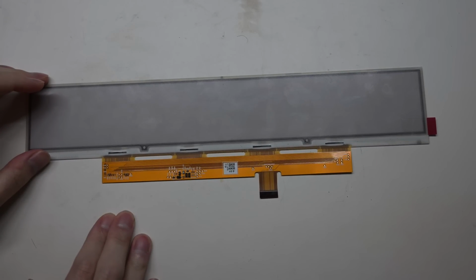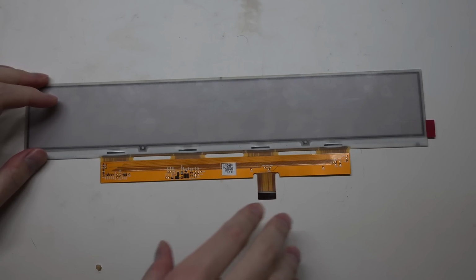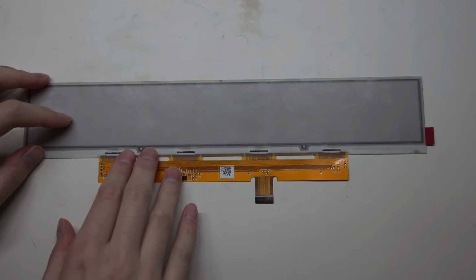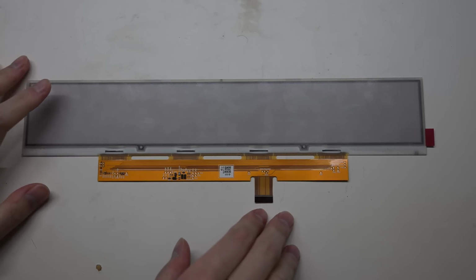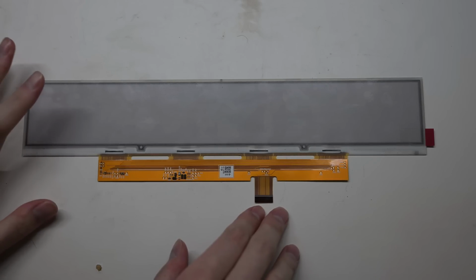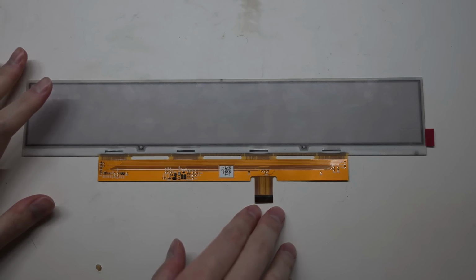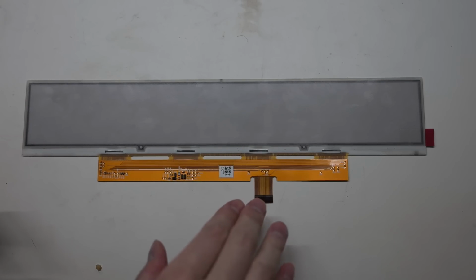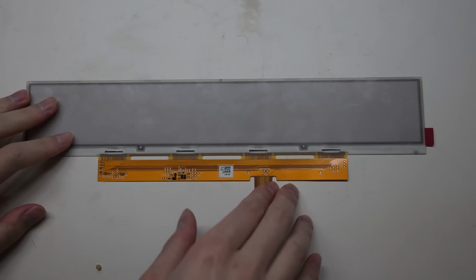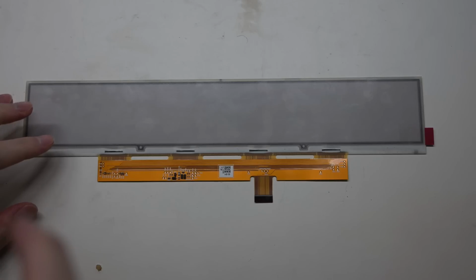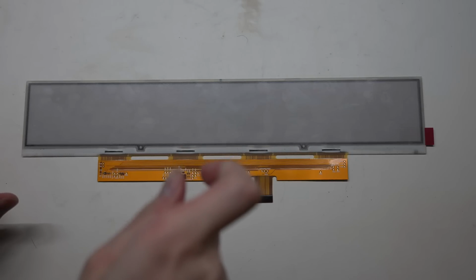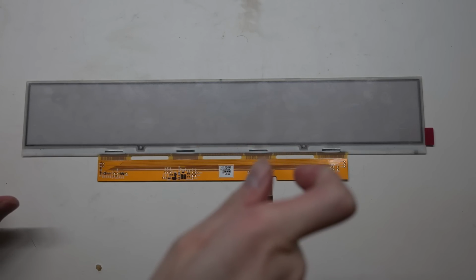So what's left? Is there any other way we can get the pinout without knowing the driver chip? Indeed, there is. One of the ways is just by guessing. This is possible in some cases. Let's say the screen has only a very limited or highly regular pinout you can see on the ribbon cable. For example, you can clearly see there are 8 signal pins followed by a ground pin, then several more signal pins.